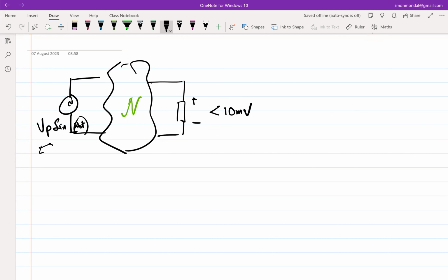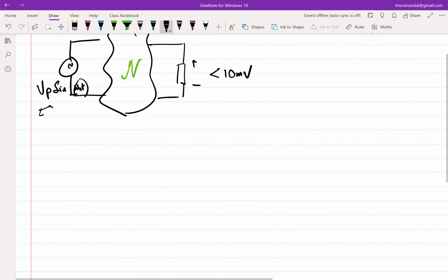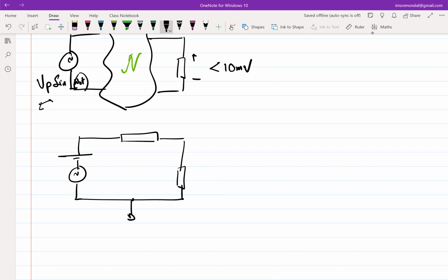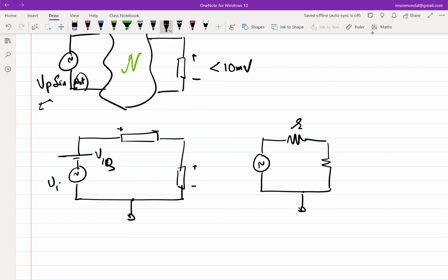And the third one that we saw at the end was this: if I have a network having multiple nonlinear devices, and I want to analyze what the incremental voltages and currents will be, given a quiescent input and an incremental input, then we saw that we could linearize this nonlinear network by simply replacing the nonlinear devices with their resistive equivalents.